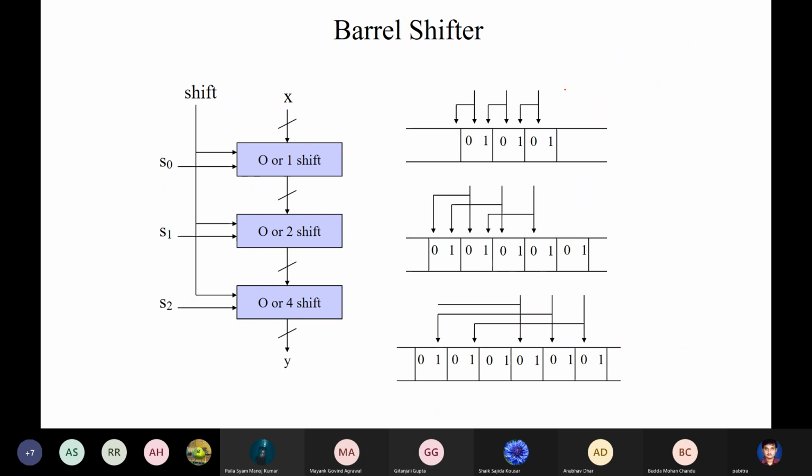There are more complex shifter designs like barrel shifters. These are a single circuit which in different modes of operation can function as a SISO, PISO, SIPO or PIPO circuit, and you can also change the direction of the shift. It's a very general circuit.